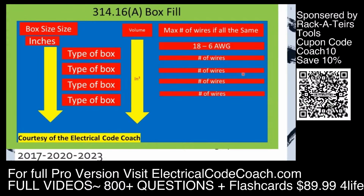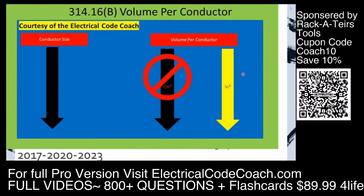It's very simple. Now let's look at the second table that we're going to be dealing with for box fill. It's right below there. It's 314.16(B). And this one's very simple to understand. On the left-hand side is our conductor size, and on the far right-hand side is going to be our cubic inch volume. Every box can only handle so many wires and devices, and that's what we're going to learn in this lesson here today. Each box has so many cubic inches that you can fill, and each conductor and device takes up so many cubic inches of that box. Now, let's do some practice questions and get to it.